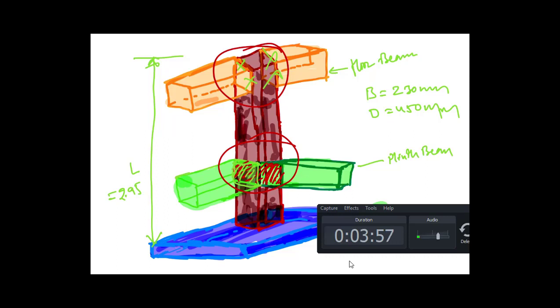So it will be a loss which has to be borne by the contractor. To minimize that, what the IS code guideline says is there is no need to deduct that, and that much shuttering area has to be paid to the contractor. After this we shall find the real shuttering quantity of a column of one real-time project.